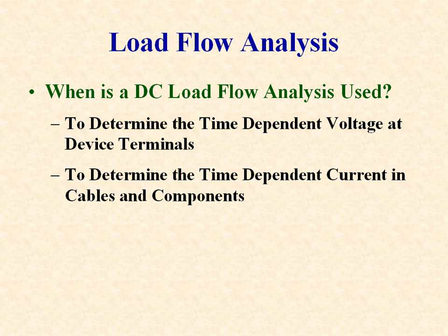The load flow analysis is used to determine the voltage at the terminals of each important load device throughout the duration of the duty cycle. The resulting voltage values can be compared to the rated voltage range for each load device. If the voltage is outside the rated range, either the system design or the component can be changed.